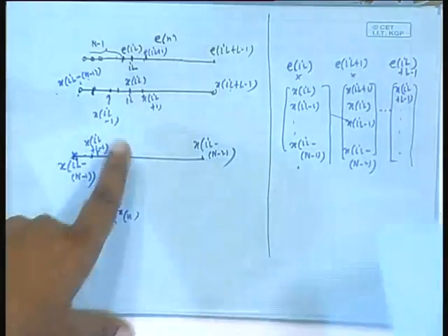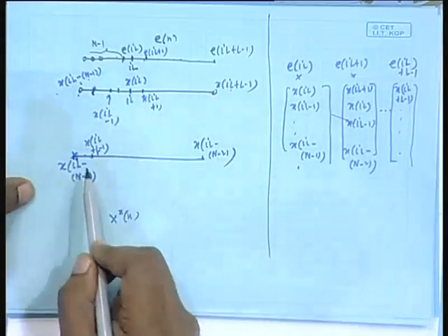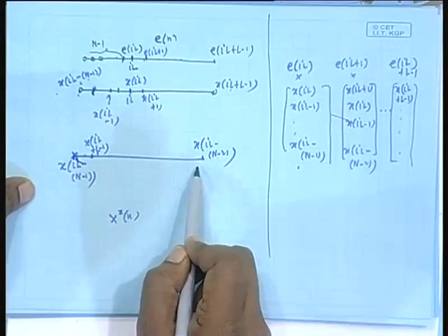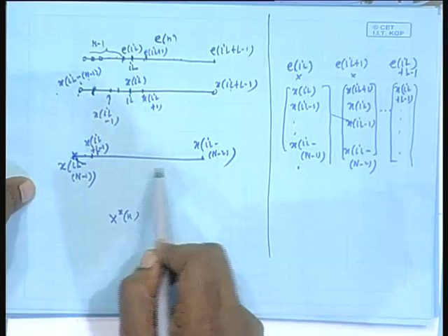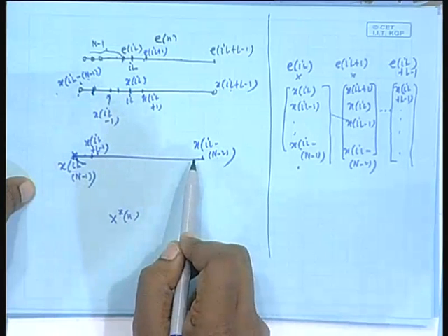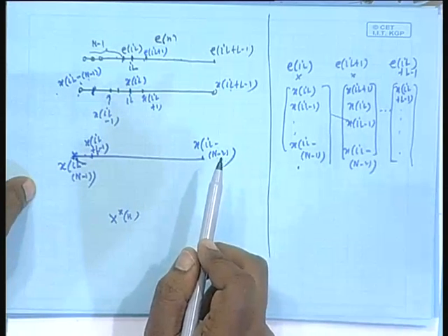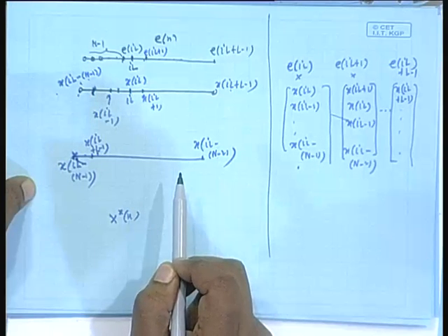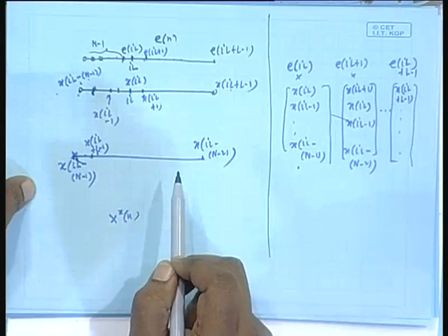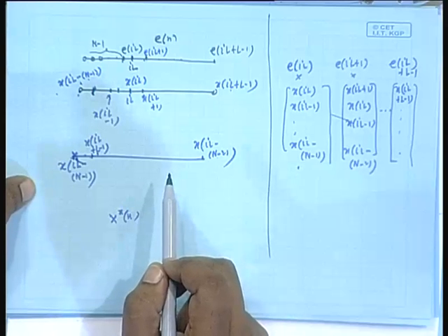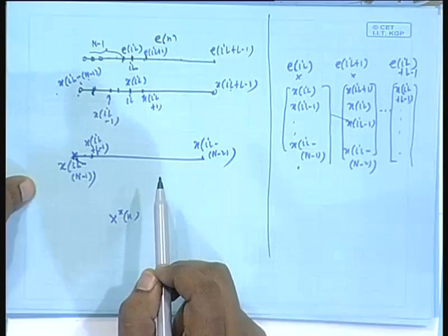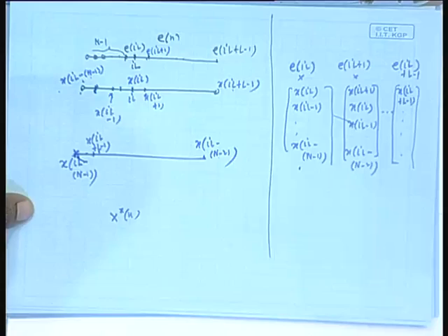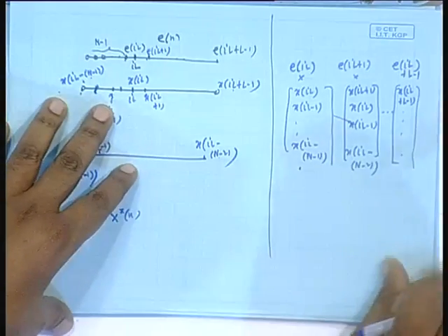Now, the claim is here to compute the DFT of this vector, I do not need to recompute the DFT of this guy. Earlier I got X k, capital S k, now it is simply X star k. Okay. So, then it amounts to a very simple thing. Let me draw the block.